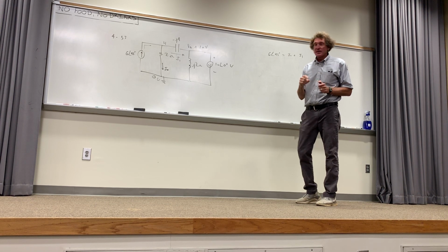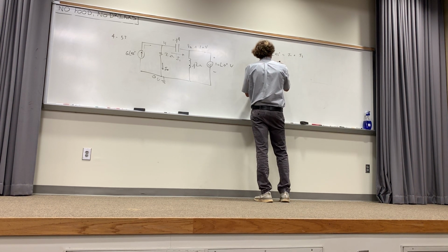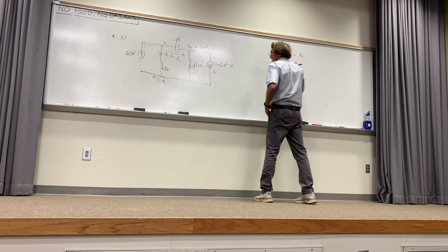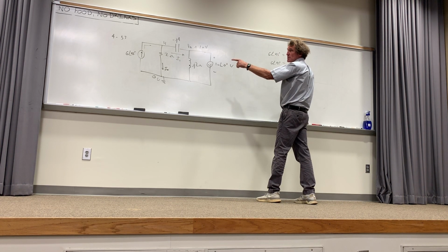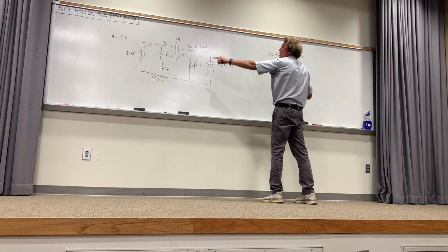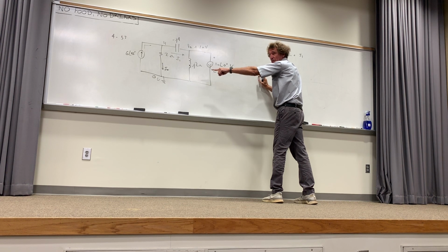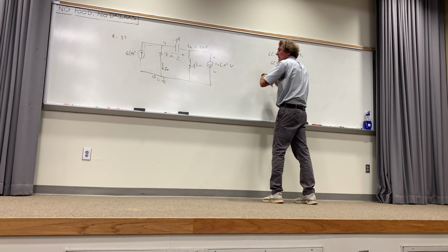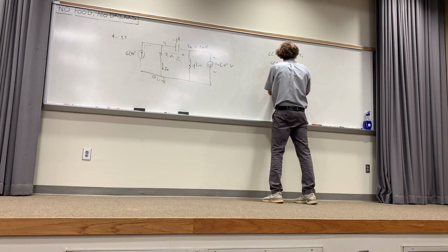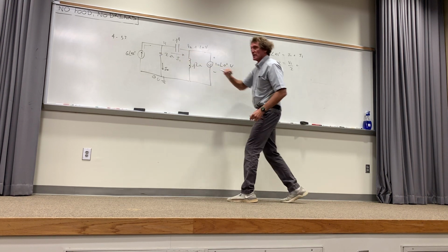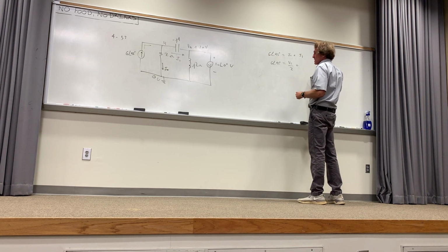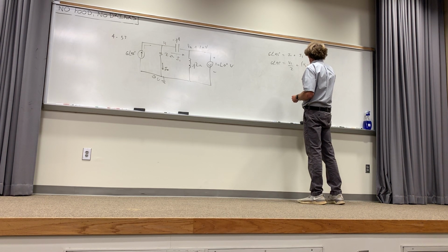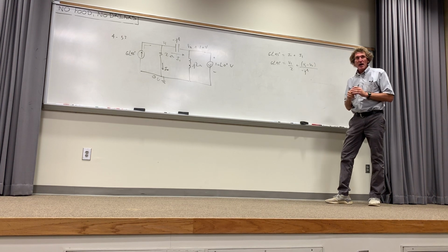Now once you have that, the next thing you're going to do is put 6 at an angle of 45 degrees here, equal to I0. Well, what's I0 in terms of the unknown voltages? Class? V1 over 2. V1 minus 0, right? Because on the other side of that resistor is 0, correct? Divided by 2, so it's just V1 over 2 plus, and what is the current flowing this way now? That would be I1. V1 minus V2 over minus J4, right? Minus J4. Do y'all follow me? Yes, sir.